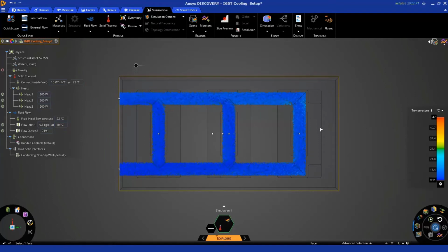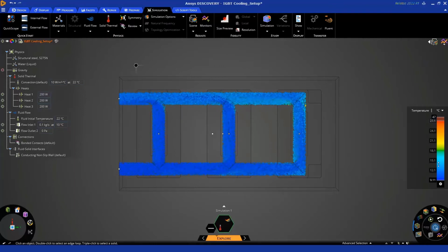As you can see, the maximum value of the legend is tied to the global domain, which is a bit too much for this flow domain, which is much cooler. You can change the peak value of the legend by simply clicking in this text box and typing a number, or you can hover over here, and as you can see, I get a double arrow, which allows me to click and drag the value.